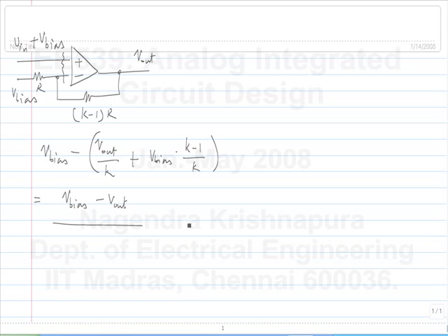So this is evaluated, of course, with the proper sign, from the plus input of the op-amp to the minus input. So now, when you evaluate it, the part that has V out must have a negative sign. That's the meaning of DC negative feedback, right? So VID versus V out, this must have a negative slope.